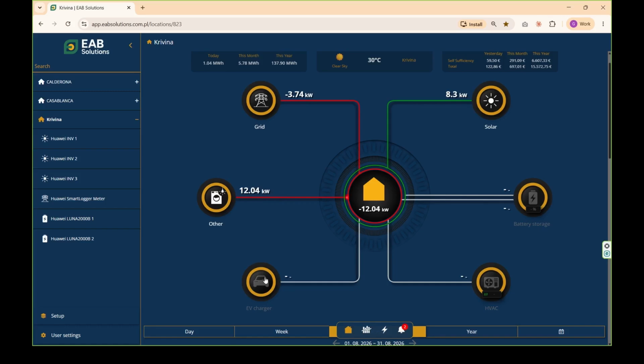We have total control over the energy management of the vehicle charging points, and the client can program those charging points exactly as they need, according to how they're going to use their fleet, what time they need the vehicles, how many kilometers they'll do each day, how many each week, and the electricity prices at any moment. It's the best way to use an EMS like this to make sure that all the energy the fleet uses has been either produced on site by the PV, or from PV surplus, or taken from the grid at the best possible moments because the price was cheap. As long as that coincides with the moment the client needs the charge.